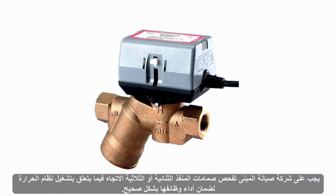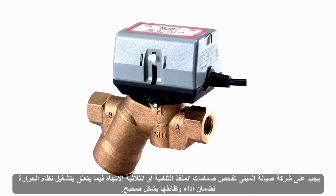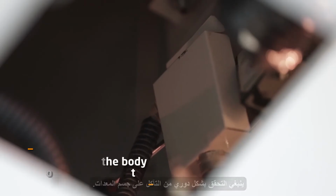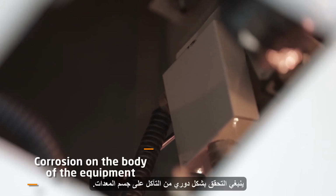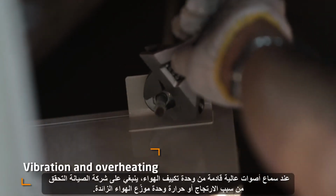The building's maintenance should inspect the 2- or 3-way port valves with respect to the thermostat operation to ensure correct functionality. Also, the bearings need to be checked and replaced if deteriorated. Checks for corrosion on the body of the equipment is a must and should be done regularly. If you hear a loud noise coming from your AC, the building's maintenance should check for signs of vibration or overheating of the FCU.